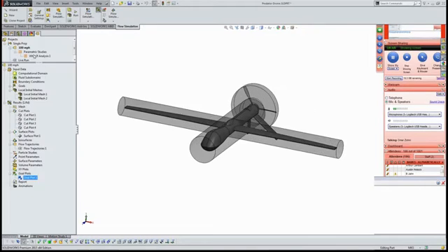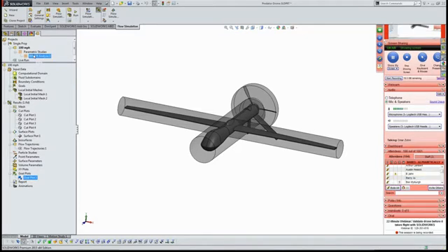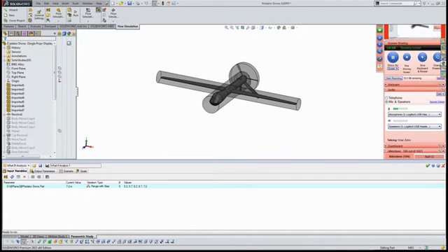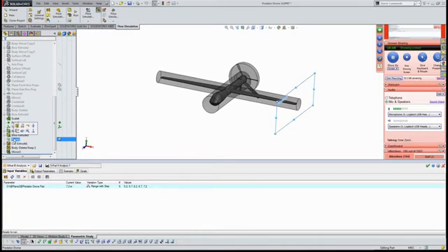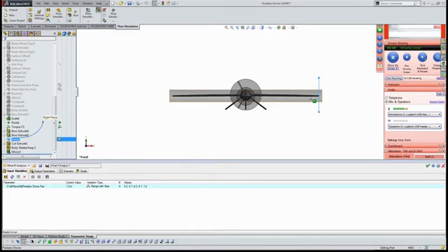So one of the really powerful things that you can do with a simulation tool that's embedded inside of your CAD package is run a what-if analysis. Now, this particular what-if analysis, because this is an imported body, I had to do a little bit of gymnastics here. What I did is I created a plane, and I basically am offsetting that plane by different values to bring it in, 5.2 meters, 5.7, 6.2, 6.7, and 7.2 meters. Then I'm cutting the wing, and then I'm mirroring the wing to the other side. So it's a way to look at smaller wing geometries, basically.